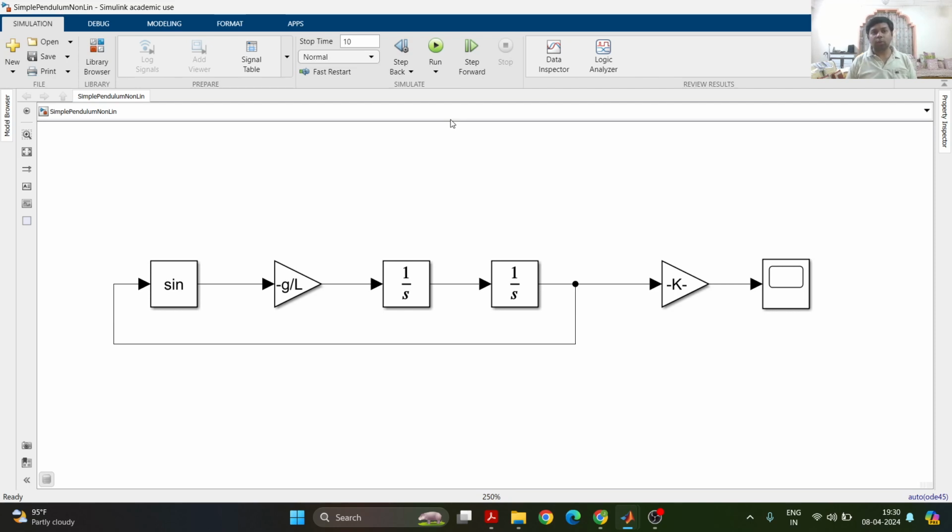We can create a relevant mat file for every model and load it in its own model workspace so that there is no conflict in the base MATLAB workspace. So each model can run individually without any conflict with each other.